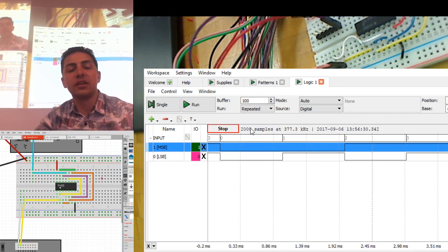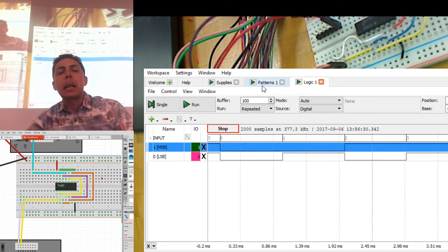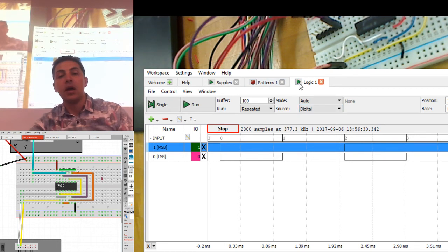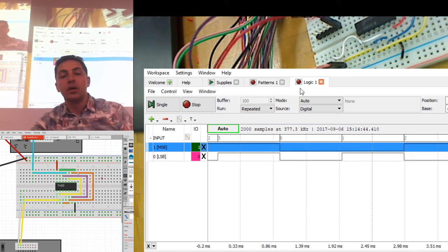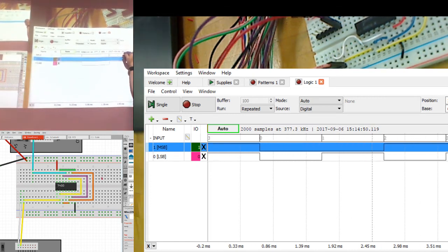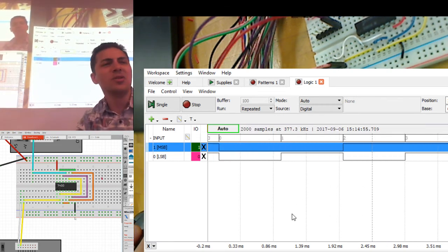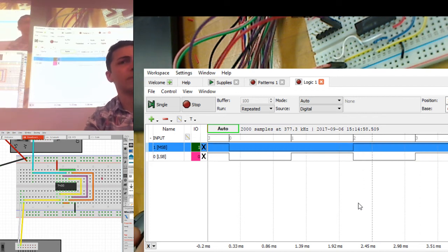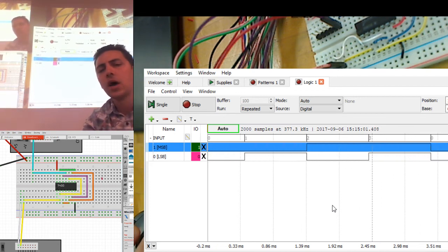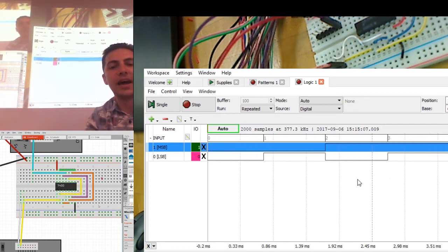And let's reset this here and add it in. Exactly the same. That is because we want to look at what we are providing as input. So if I turn the pattern generator on and I turn the logic analyzer on, you can see that it's running. Okay, there's a time base along the top here. It's triggering, I don't know, 20 times a second visibly, doing 20 waveforms a second. But can you really see what's going on here? Does it seem like it's imparting any useful information? No. That's because it's just triggering as fast as it can.